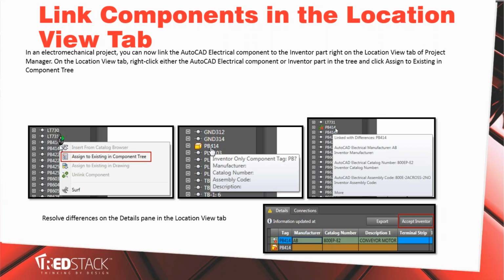If you do that, then sometimes you create a new component inside Inventor, you bring it into Electrical, and it couldn't recognize it. It asks, what is that connector? So you can tell that this Inventor 3D model is actually that 2D symbol in AutoCAD Electrical. You can assign an Inventor component to an electrical 2D component, so they know that this connector in 2D is that connector in 3D. To assign it, you just right-click on the Inventor component and select Assign to Existing Component. That's it, very simple to use.